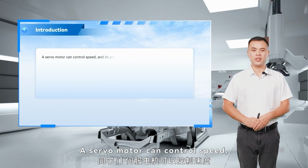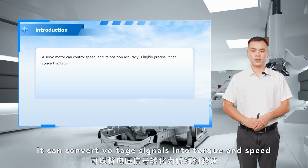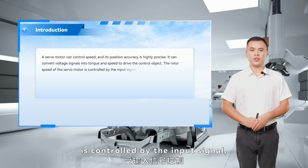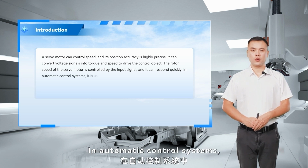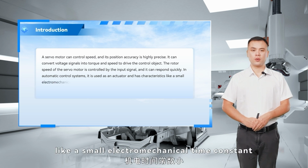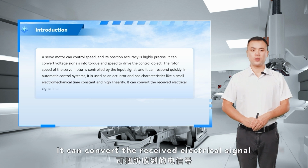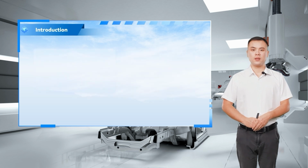A servo motor can control speed, and its position accuracy is highly precise. It can convert voltage signals into torque and speed to drive the control object. The rotor speed of the servo motor is controlled by the input signal, and it can respond quickly. In automatic control systems, it is used as an actuator and has characteristics like a small electromechanical time constant and high linearity. It can convert the received electrical signal into angular displacement or angular velocity output on the motor shaft.